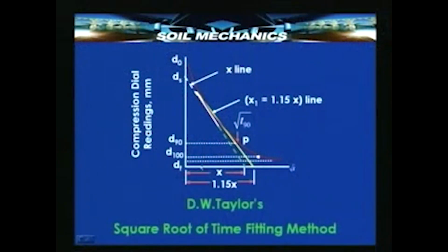This phenomenon of secondary consolidation starts at the end of the primary consolidation, and as can be seen in this figure, df corresponds to the point of secondary consolidation completion. So, starting from ds, which corresponds to 0% consolidation, we have 90% taking place up to this, the remaining 10% taking place up to this, and then the plastic lag taking over and the final compression ending up here.